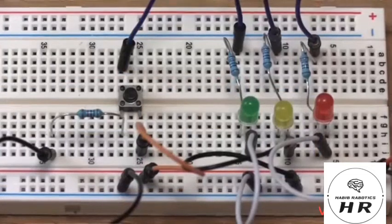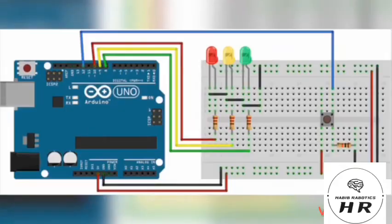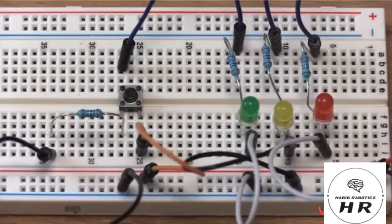Now let's add a simple button to the project, the idea being that when the user presses the button, the traffic lights will change. The Fritzing diagram in the article on the MakeUseOf website will show you how to set this up, but very briefly, one side of the button has the power and then it goes to ground through a 10k resistor, and the other side of the button has the line which runs to our Arduino. It's set up this way so that the Arduino gets a clear signal of when the button is pressed.